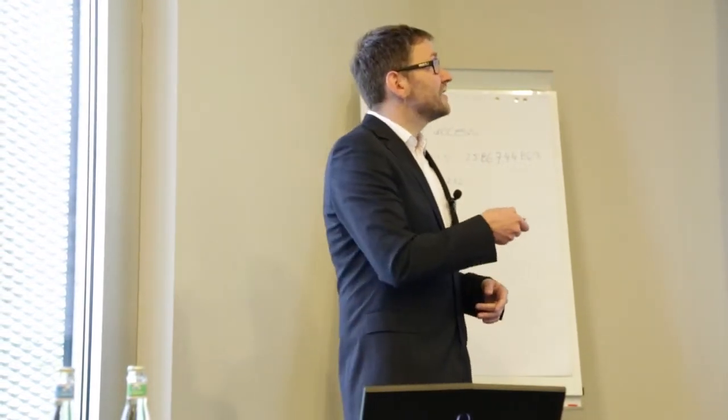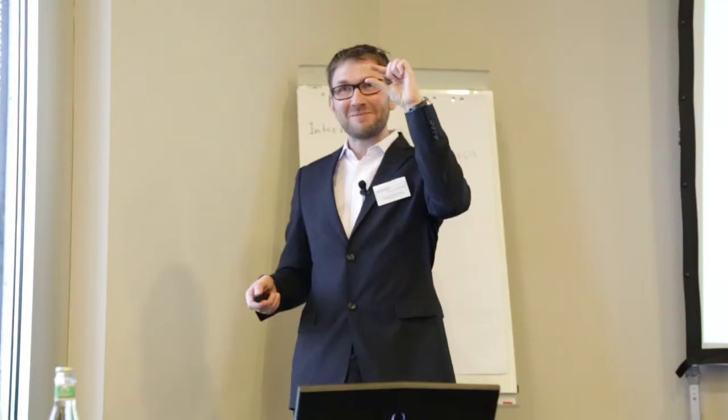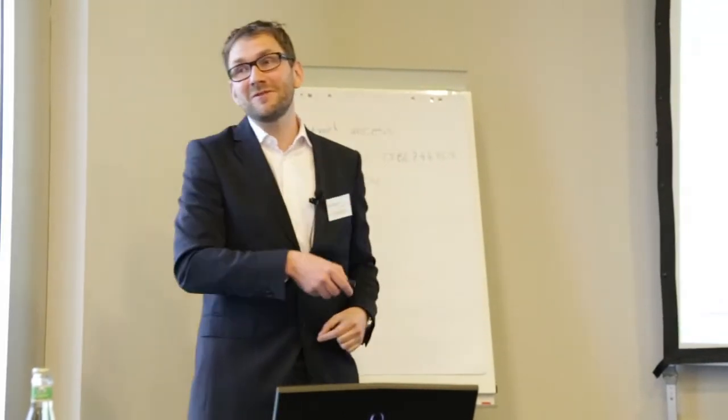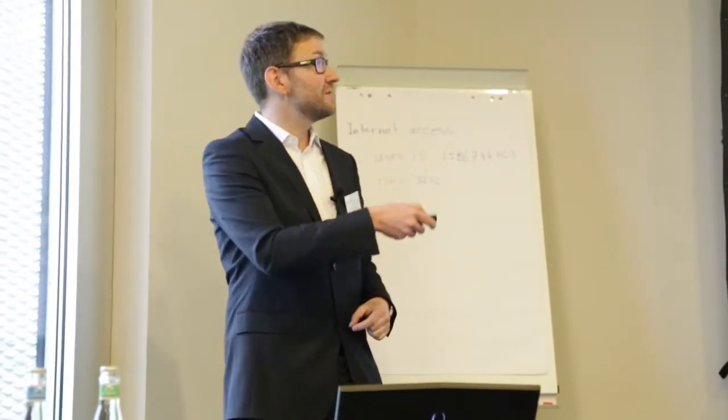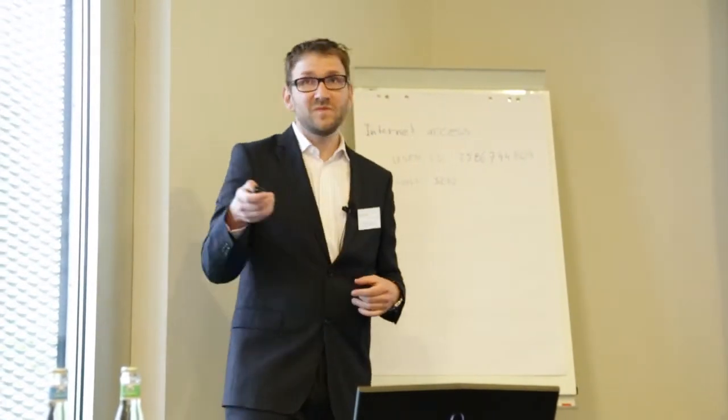Here again, you see a basic intrinsic property of the cement hydration, which is this calorimetric curve. In principle, there's a lot of debate going on about how this curve should look, and how you can relate the different peaks to the different phase evolution. But for the engineers, the real value is the area underneath. And this area you can easily measure with calorimetry, and on a sample that small, you can derive very nice properties related to structures as big as a dam. And these tools were quite successful.